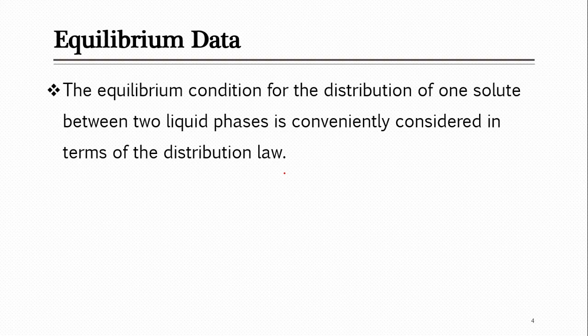The solute is in small amount while the carrier is in large amount. We bring this in contact with another solvent, introduced to remove the solute from the feed towards that solvent, and then we finally separate it. So this is actually a ternary system, which involves two components of the feed and one component, the solvent, introduced externally.